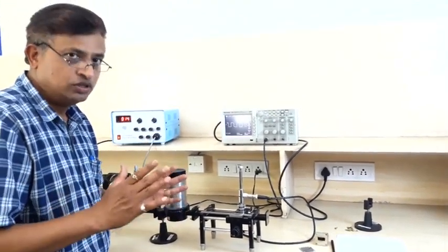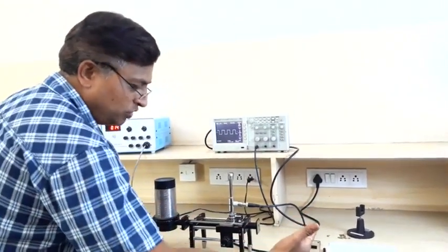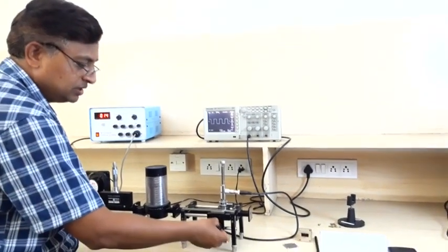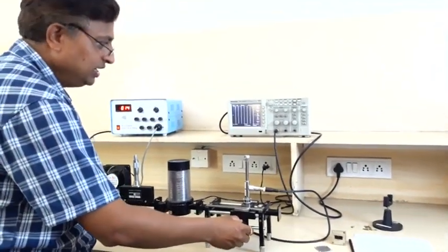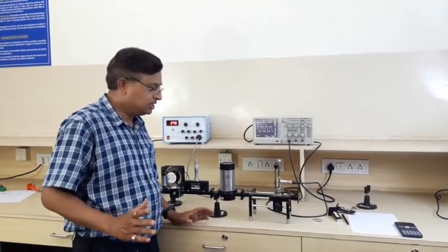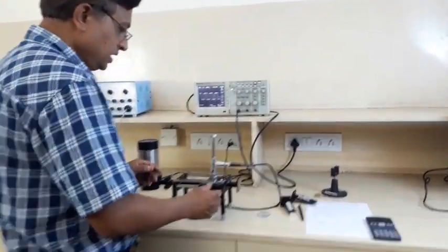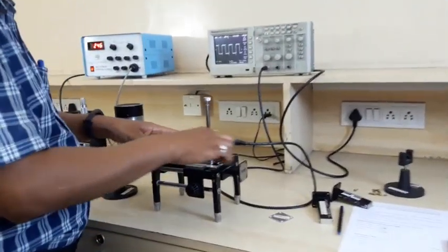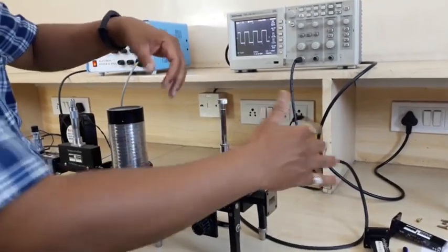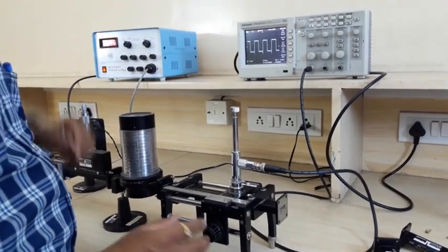Now let us move towards the measurement from the extreme load side towards the source side by moving this knob slightly and keep observing the oscilloscope. Let us measure the condition for open termination. The tunable probe is connected to the slotted line section, and the output square wave you can observe on the oscilloscope with its magnitude.